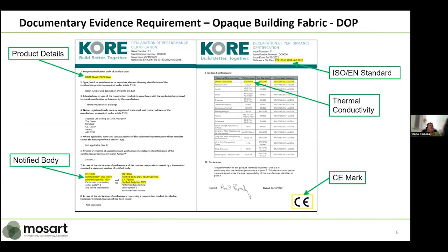The other type of information we can use here is a declaration of performance. So here's one for Core EPS 70 Silver. Again, a product many guys out there will be familiar with. Again, you've got the product information. In this case, there's a notified body which serves as evidence that the product has been properly tested. We have the ISO standard noted there on the top. We have the thermal conductivity provided, and that document is CE marked.